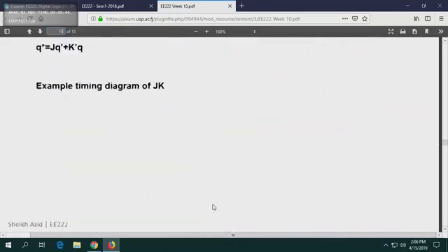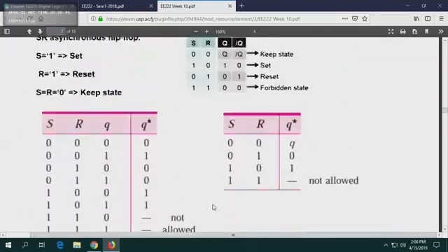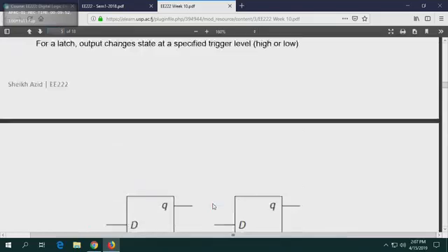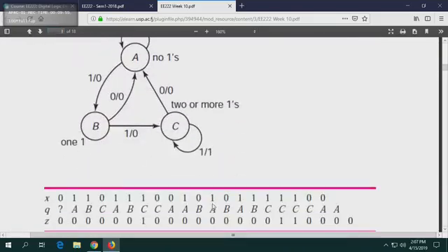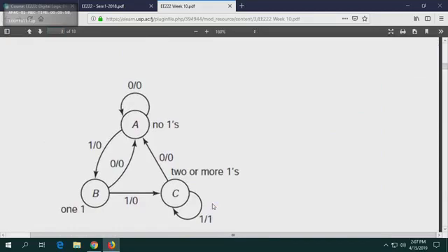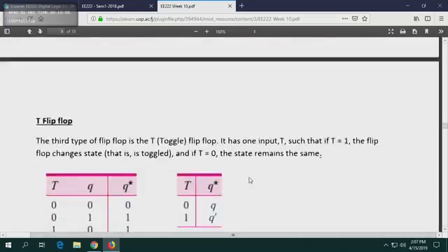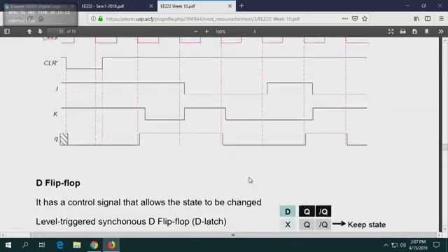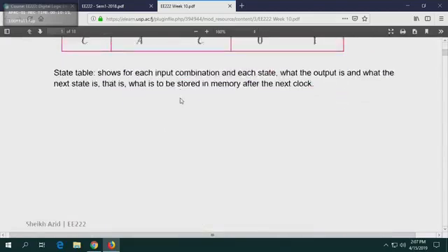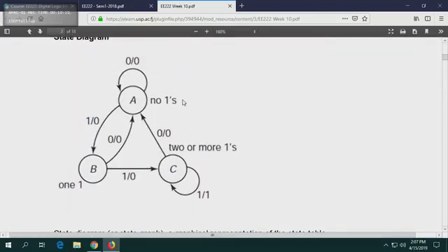A state diagram looks something like this. We want to end up with something which looks like this. That's a state diagram, and I'll teach you what a state diagram is. The way I'm teaching is, I'm teaching you the theory as we go along with the particular example problem. Now, the other type of problem is that the state diagram is given, or the sequence is given, and you're required to draw the circuit, go backwards. So that's a design problem.